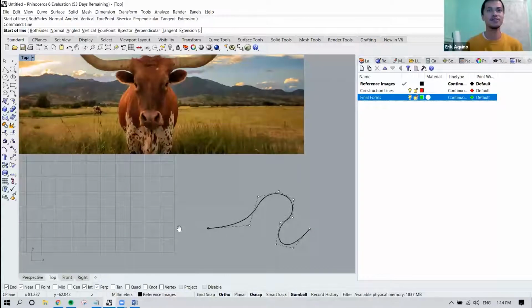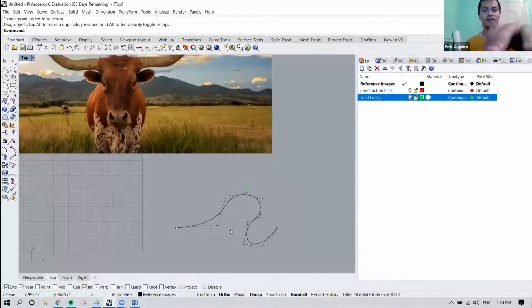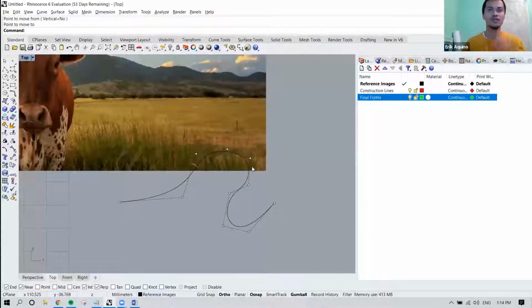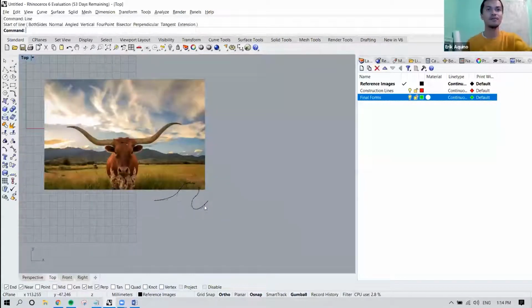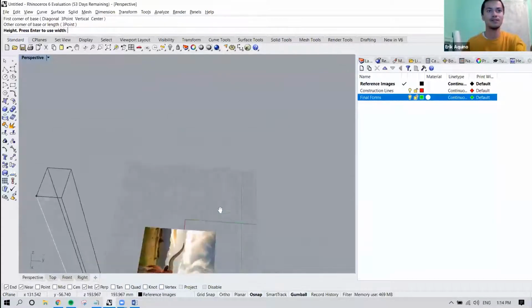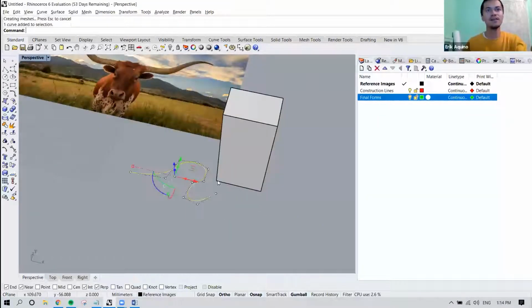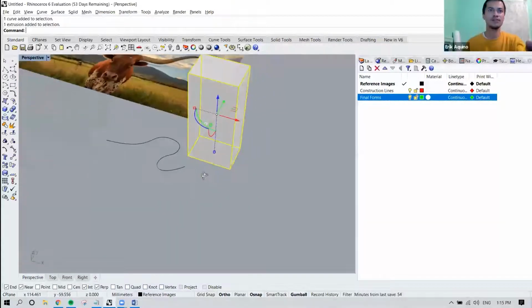And my intersection would just mean this. Intersection just means if I have two objects intersecting, I can select at that intersection. But be wary because when you have intersection on, you could also have apparent intersection. So I'll show you what that means by drawing this box. So physically, they are not intersecting. They're in two different spaces.